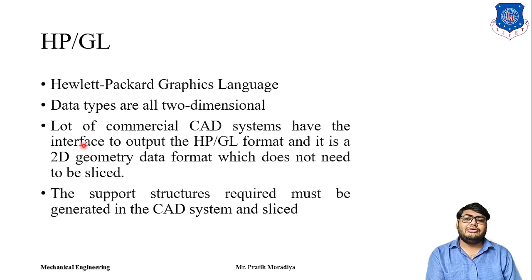So you need to store multiple HPGL files, and you need to give them some sequencing, so that each layer will have that logical sequence, and each layer will be produced number by number, each HPGL file one at a time, because each HPGL file is 2D data, so you need to stack all the HPGL files to produce an entire